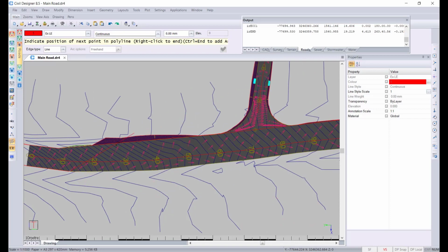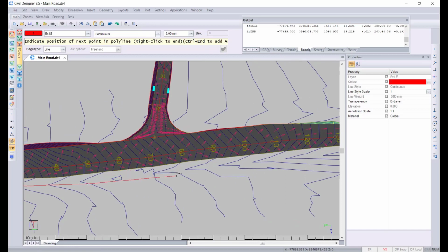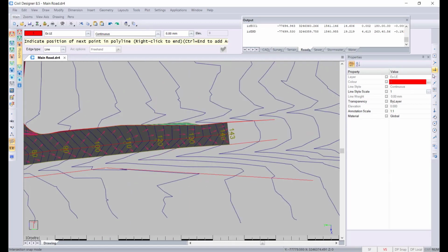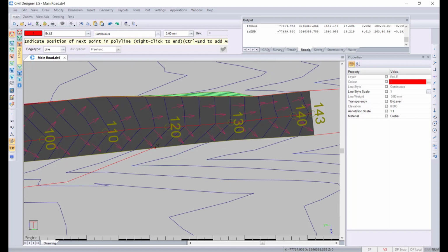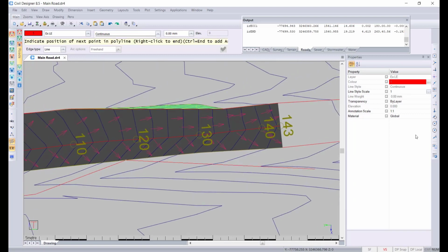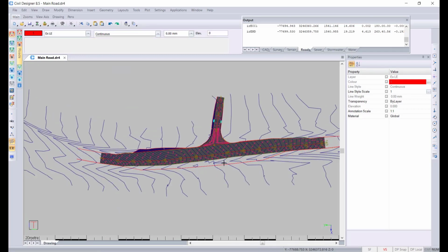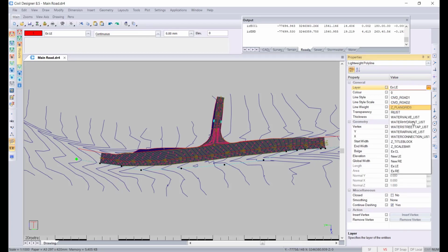and I'm going to go back to freehand mode and then put in the extra lanes so that there can be a refuge island on the existing roadway, and then a taper back onto the existing. So I'd like to use the nearest. You can work more precisely. It's just to try and save time with this. And I'm going to use the snaps again, snapping on all the edges that are available. And I can then press escape. And I'd like to make sure that this is in new right edge.